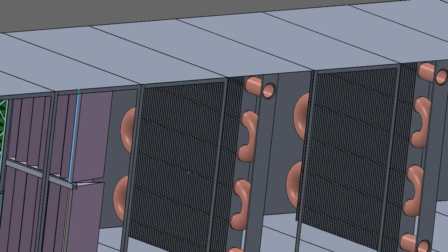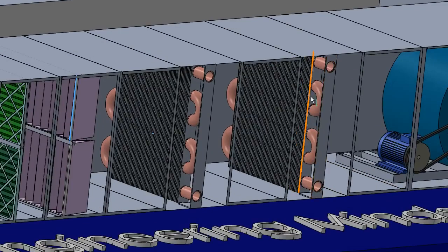With your heating and cooling coils, obviously the heating one is going to be connected to your boiler or your heating system. It could also be electric, an electrical heater in here, certainly for frost protection that's sometimes used. And the cooling coil here is what's going to be connected to your chiller or your chilled water system. If you remember back to the beginning of the video, that's what's coming off that riser, the chilled water coming in and passing through.